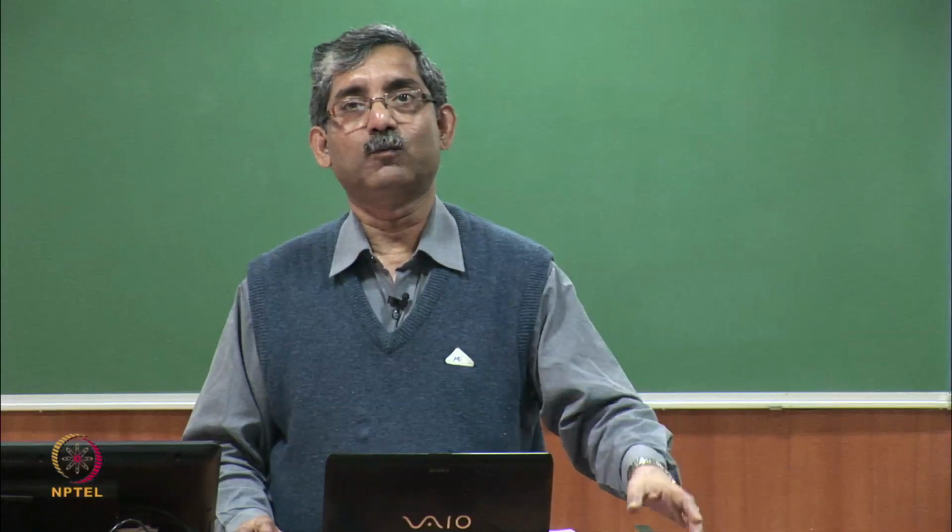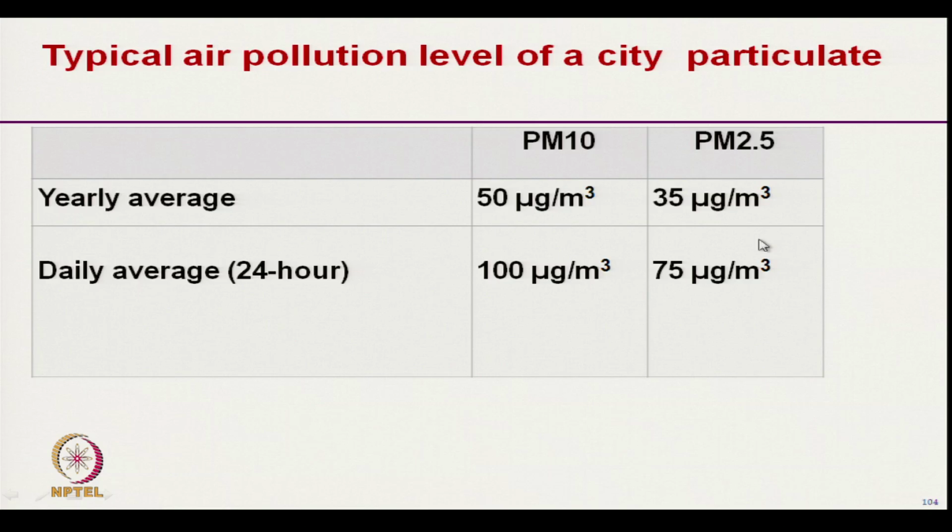PM 2.5 will definitely be less than PM 10 in value, because it covers only particles of 2.5 micron or less. From here we can see that in the air the majority of particles are of size 2.5 micron or less. That is obvious, because larger particles normally settle due to their mass.